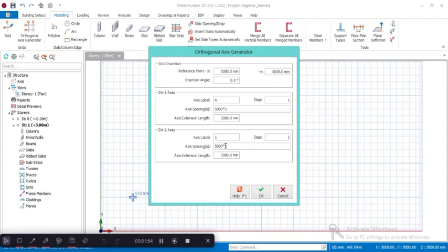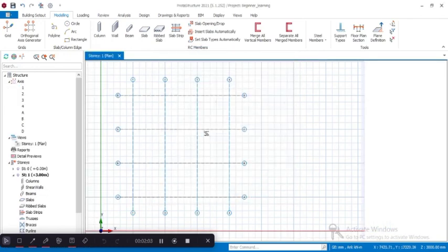So here it's showing us 5000 by 3. So it's going to be 3 lines here and then 3 lines up. So the box is going to be 3 and 3. This is 1, 2, 3, 1, 2, 3. So it can be edited though, if you want it in more numbers. And the span can also be edited, as we saw there, 5000. You can change it to whatever you want to use there. Orthogonal gives you the spacing. You've already put the spacing, so it's equal at all points. That's how it goes. So that's what we're going to be using for this beginners class. So now let's resume where we stopped.